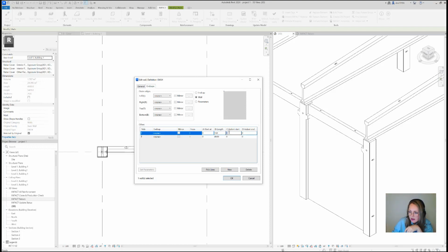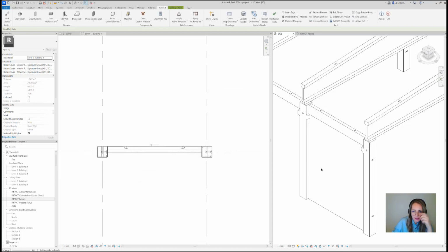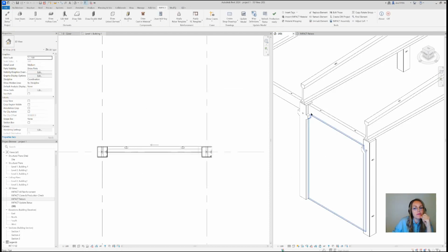I have some numbers here which are going to help me define the recess that I need for the corbel, and you can see it's kind of, you already see it here in the top. So we're adding in cap on the top from left, and you're gonna need the same because there's another corbel on the other side. If I fill in the numbers and press OK, what you're actually getting is the recess.